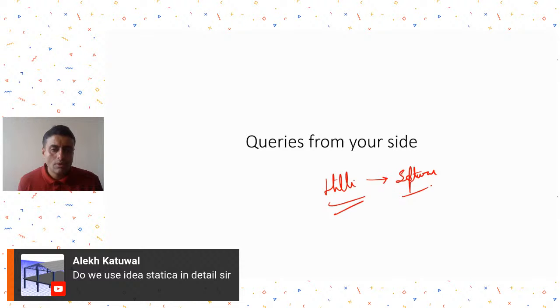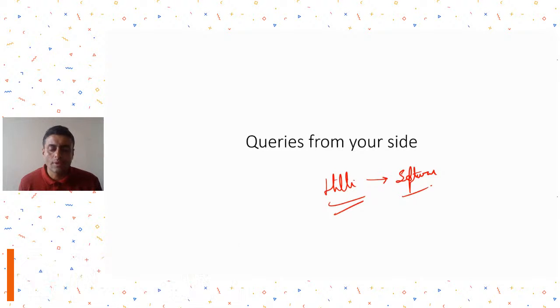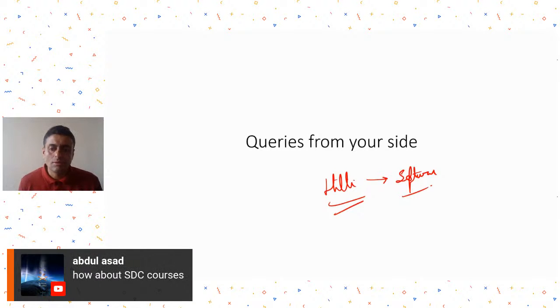Alec is asking, do we use Idea Statica in detail? Of course, in great detail. We'll see the workings of the software in great detail. It's a finite element based software, so they call it the component based finite element method. It actually depends a lot on the mesh sizing and mesh convergence, and there are a lot of those issues. So we will discuss Idea Statica in great detail.